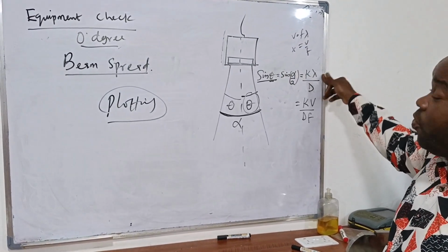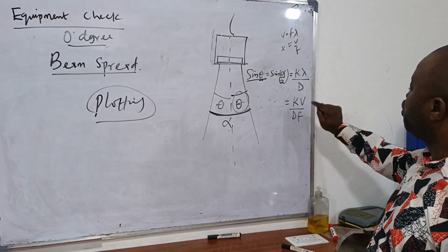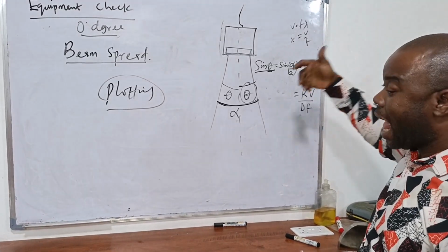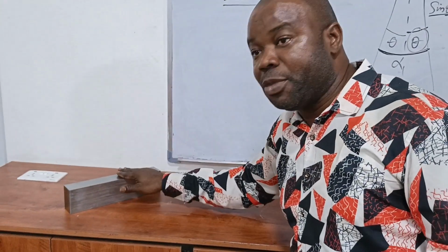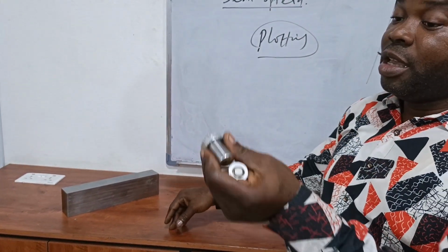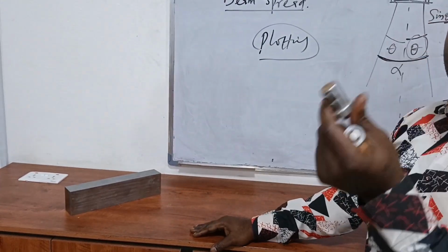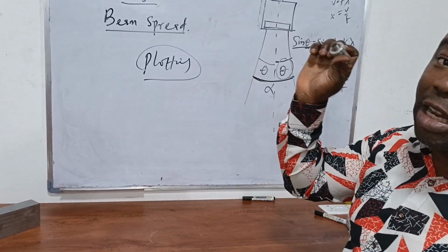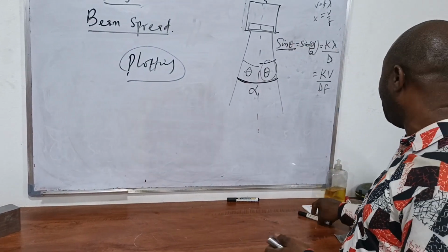If you put it into this formula, you are going to get this. So put in the value of the frequency, the diameter, and the velocity of the material, because you are using 0-degree. If you are calculating beam spread for an angle probe, please note the difference in the velocity that you are using. But since we are talking about 0-degree, we can use our normal 5920.